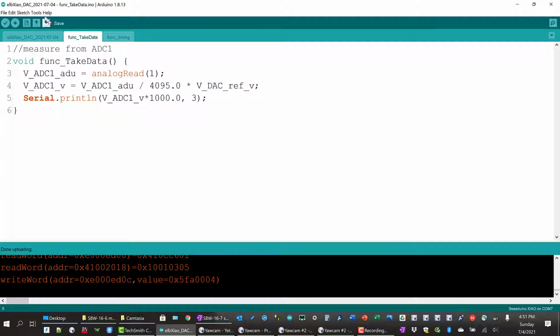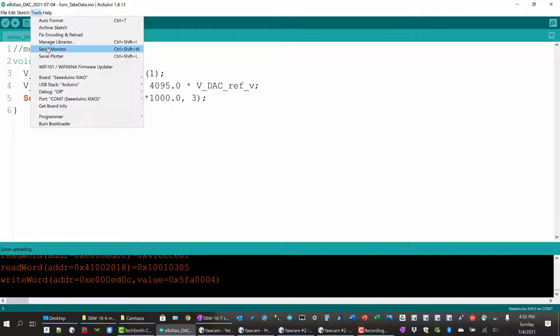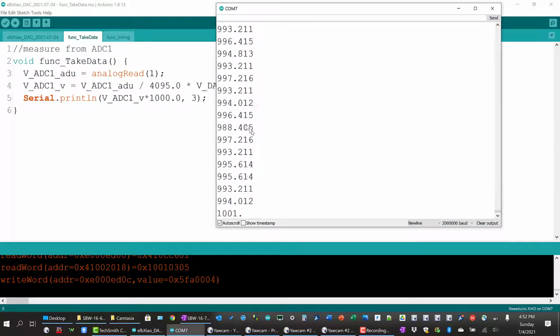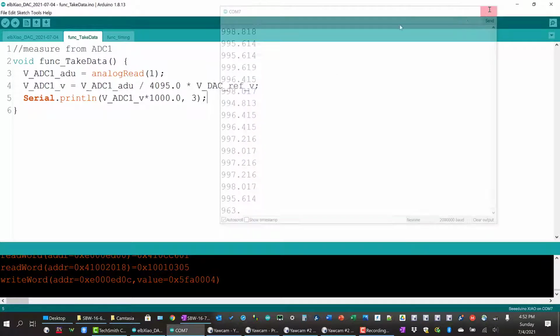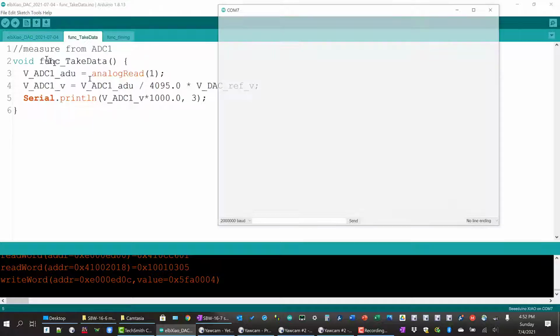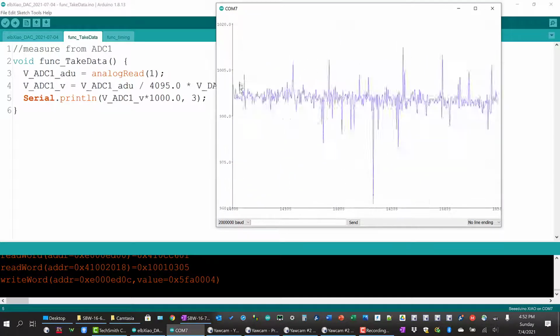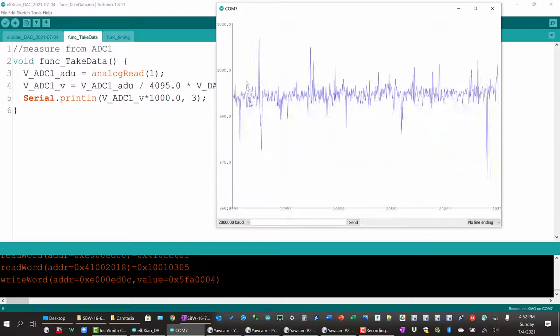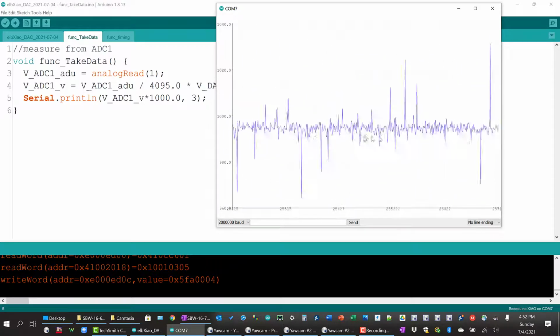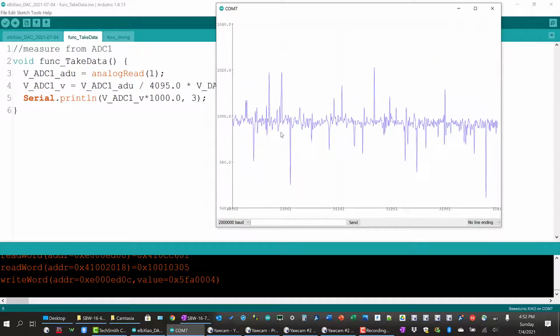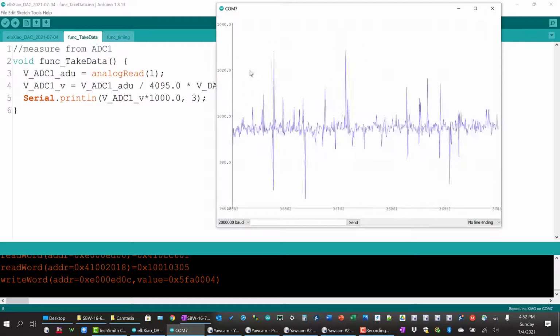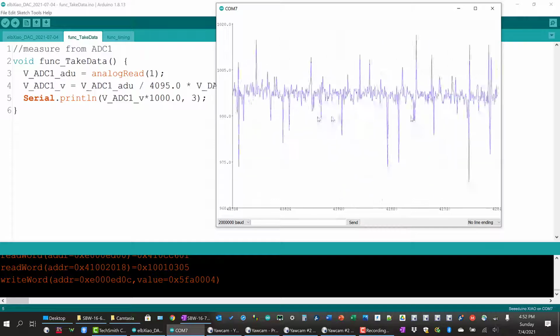Okay, done uploading. We know what we're going to see if we look at the monitor. We're going to see all the millivolt values. Here are the millivolts. So we have large numbers, and we can go ahead and plot those at 3 millivolts per division. So we close the serial monitor. Now we open up the serial plotter, and here we go. We're on average at about 25 millivolts per division. You see all the noise. You see the data going by really, really fast. Gosh, it's really hard to make sense of it. We have the combination of the scale changing, and it's going by really fast.